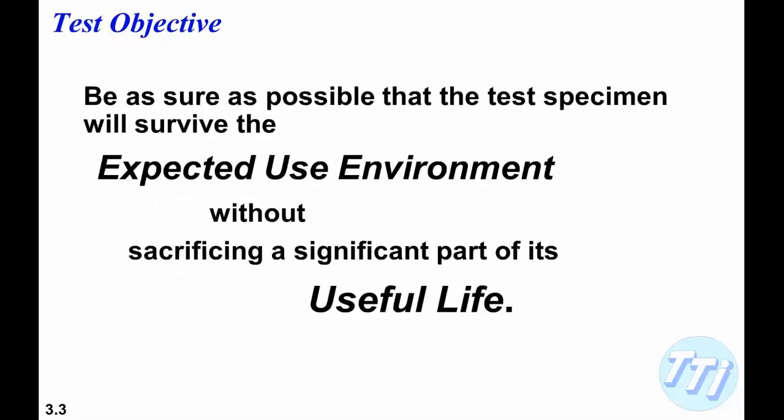So the objective is to be as sure as possible the test specimen will survive the expected use environment without sacrificing a significant part of its useful life. So this is a tightrope that we have to walk to be sure that we aren't damaging the specimen, but putting enough stress on it so that we can assure that if it is going to fail in service, it will also fail in our testing program.